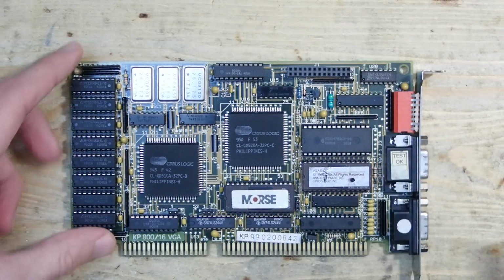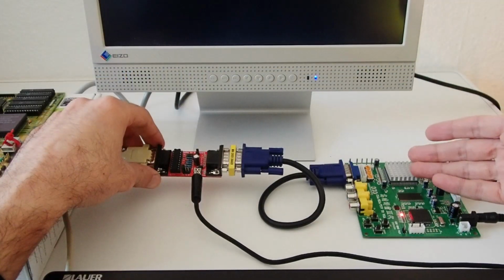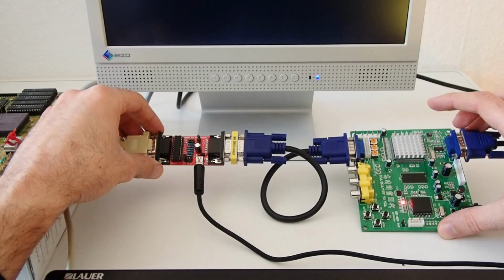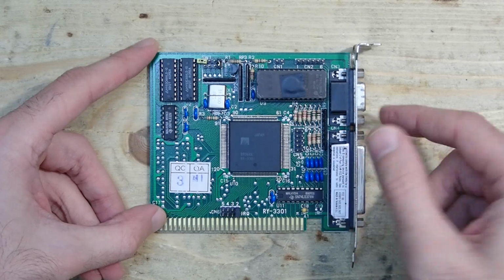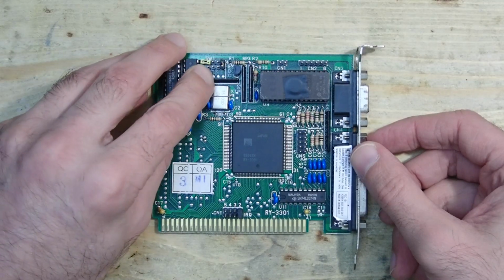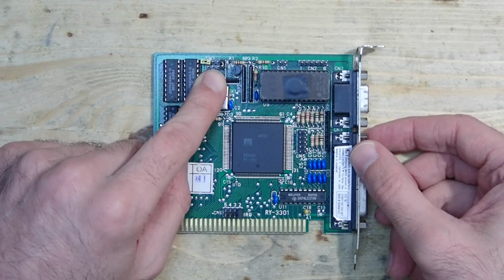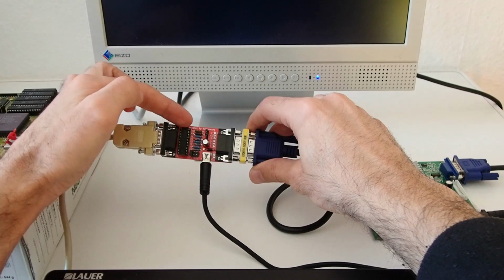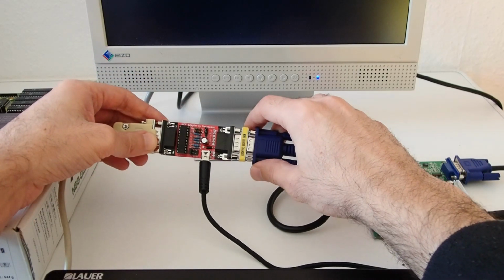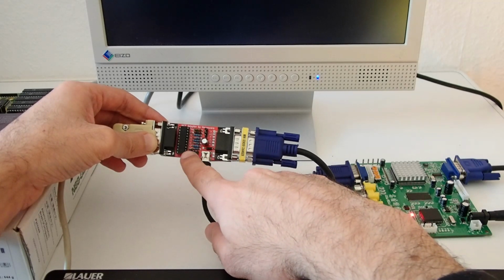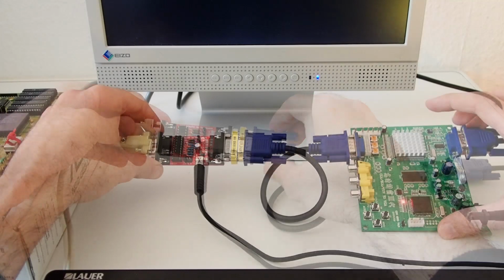Okay, let's connect the MCE adapter to the gbs-8200 and see what we get. First graphics card will be the Hercules and CGA compatible one. It is set to auto mode, so we can switch between Hercules and CGA from the software later. On the MCE adapter, I'll set the first jumper to color, second jumper to unset, since CGA can only do 16 colors, and the third jumper for sync inversion is also unset. And this jumper is set to composite sync.